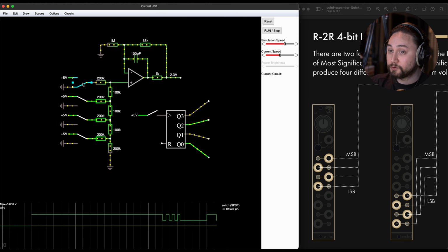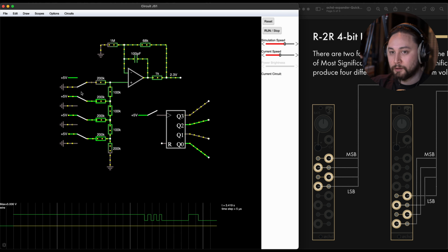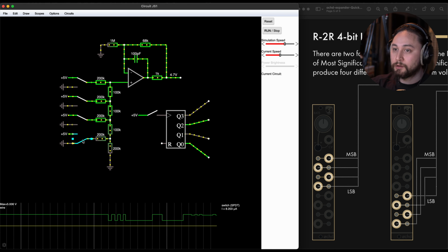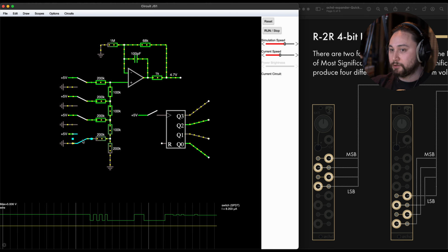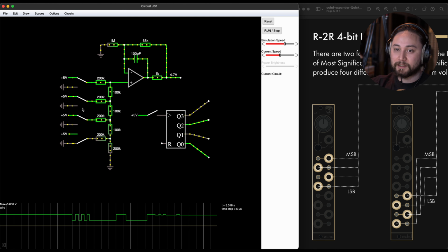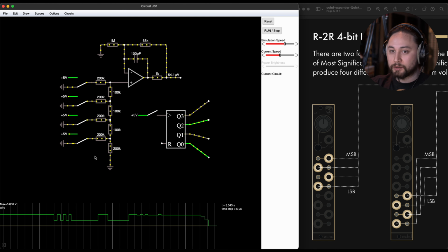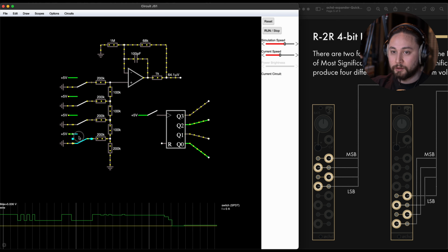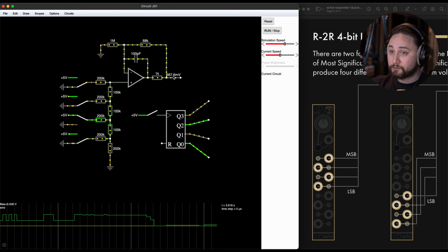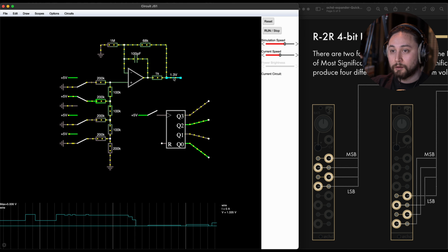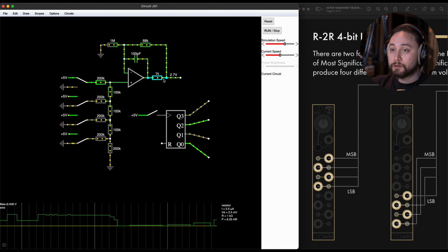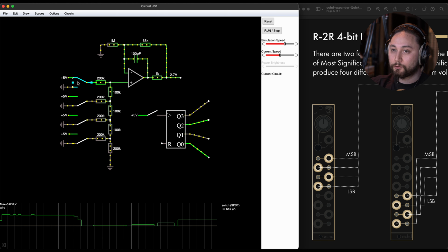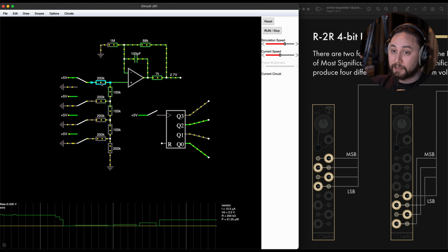So if we go from 5 volts, if I turn this off, it jumps down to 2.3. Least significant, if I change that, we're just getting deviation of 1/3 of a volt. So each bit's magnitude from least significant to most significant has a weighted amplitude range to it. So if we look at just the LSB on its own, 333 millivolts, so that's 1/3 of a volt. If we look at this one, 667.6, so that's 2/3 of a volt, 1 volt and 1/3, and then this one, 2 2/3 volts.